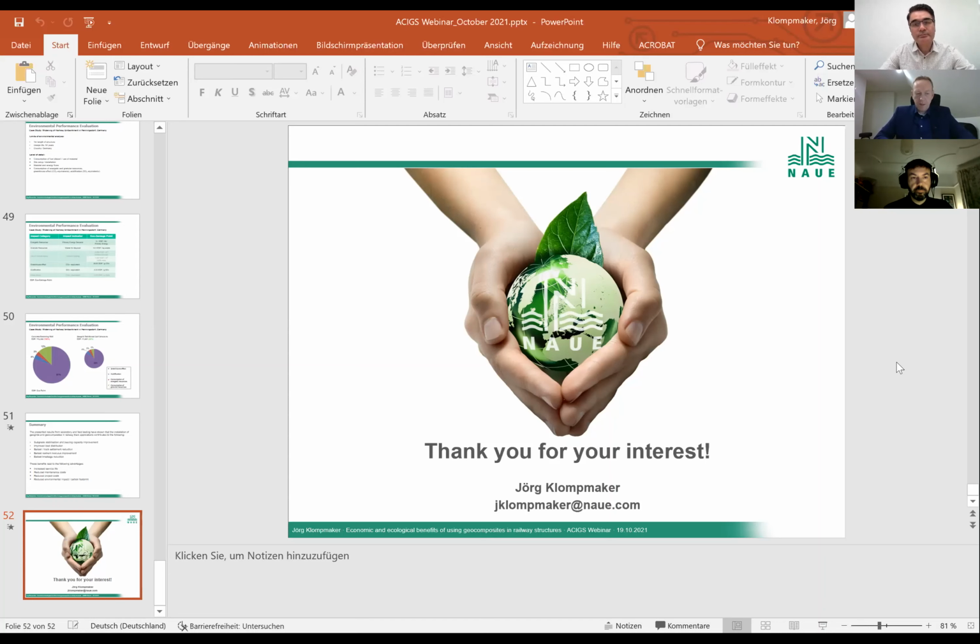It is, but it's similar like with geosynthetics. There is a difference in different geosynthetics. I already mentioned that the stiffness property of the geogrid will have an impact on its performance, and the same we have with soil. So if we are using a lower quality soil, like in your example, if we are using sand instead of a crushed stone, this is a reduction in stiffness of the material. The geogrid will still provide benefit because we have the reinforcing effect that we can quantify for this material, but